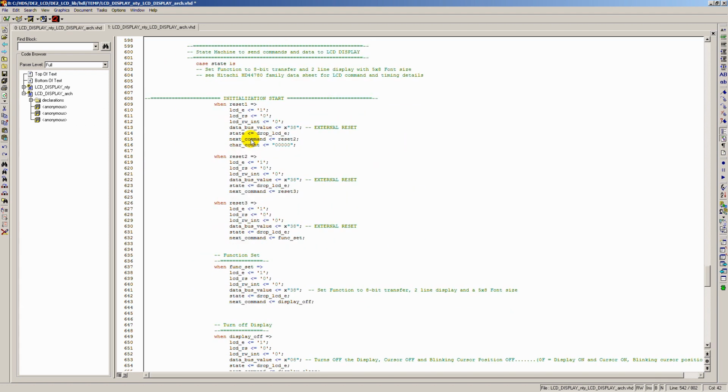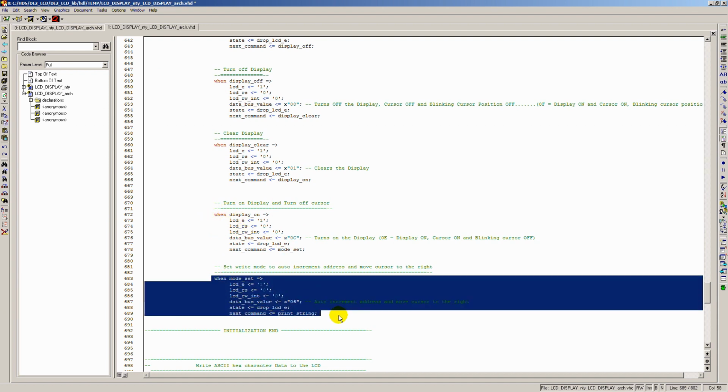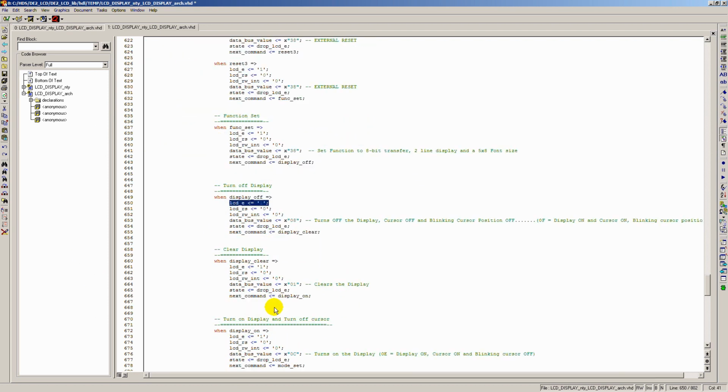And I'll explain why. When I was manipulating things around, I added an additional state to the state machine. So we ended up having 3 states being executed one after the other before the next command would run. That extended the period of that signal.